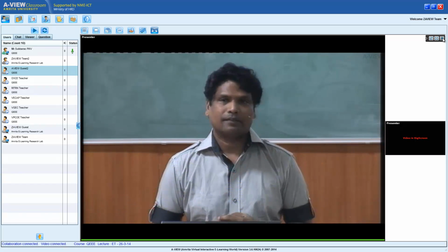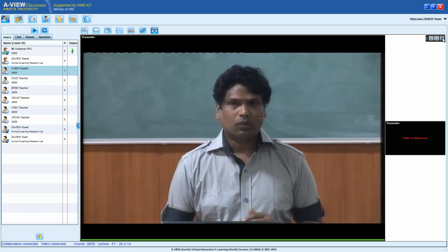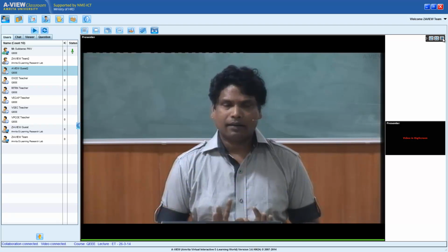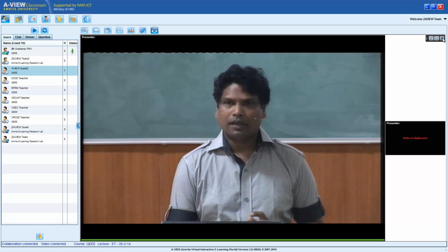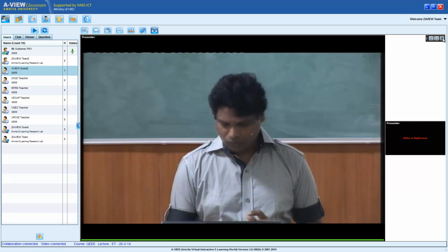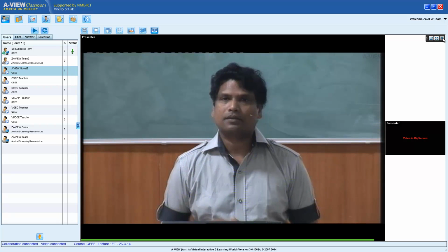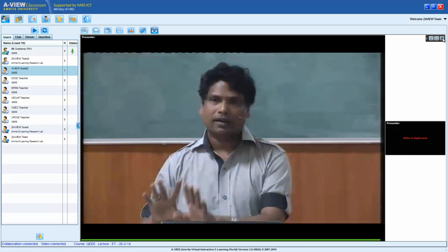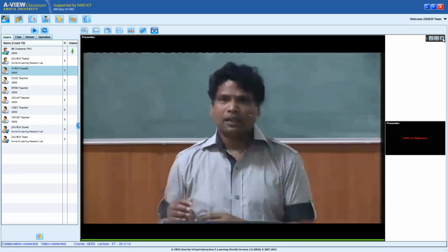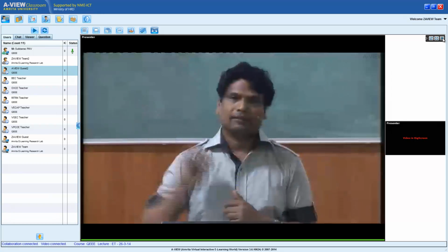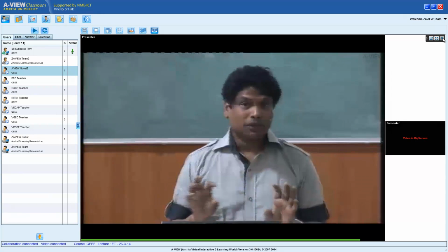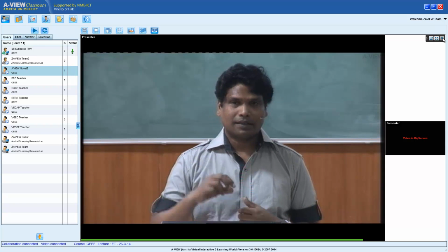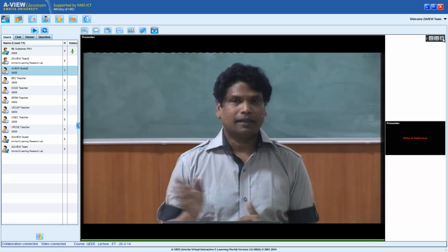This is one strategy. Now the next one is, I don't want to have any drum and storage, nothing. The water continuously enters and goes through the continuous tubes. And in between I am burning the coal and making all the heat to be transferred to this. Now in this case, continuously the fluid is moving. So you see, both are control volumes because something can leave or something can enter.